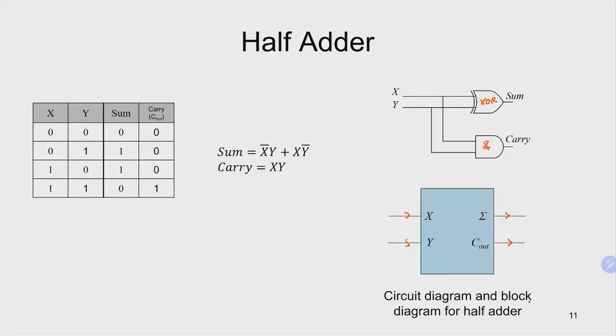And this block diagram, or this circuit, is called a half adder. Okay, so this is one simple system. We have a combination of logic gates that give us a small simple system that performs a half adder. We'll look in a minute at why this is called half, and we have a full adder in the next couple of slides.